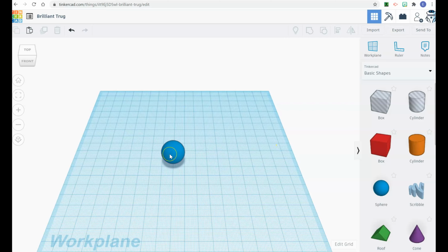Okay. A few other things here. If I want to make a copy of my object, so I've just loaded a sphere onto my platform, I can do a couple of things. I tend to use shortcuts like Control-C for copy, Control-V for paste. Works the same way in probably all the Microsoft applications. That's very handy. I can also do a duplicate with Control-D, and I can also use my keyboard to delete an object. Tinkercad, though, also has a few other commands on the menu bar that do the same thing. So you'll see up here on the top left, there's the copy for Control-C.